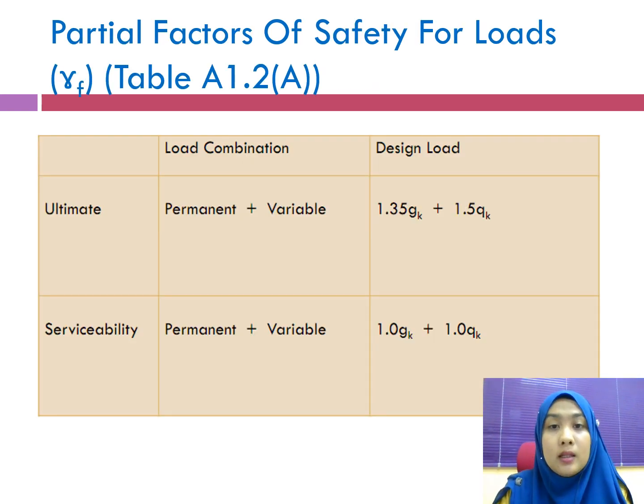Okay, so the next one is partial factor of safety for loads, the loading on the structure. The load combination for ultimate limit state has permanent load and also variable load. Design load at ultimate limit state is equal to 1.35 GK.